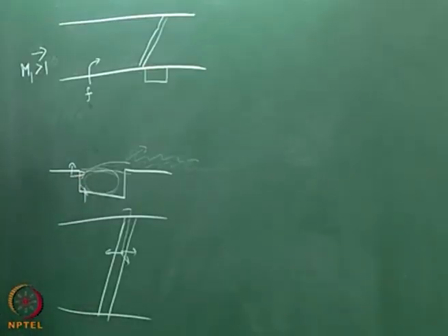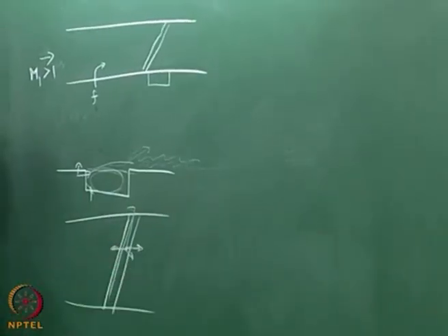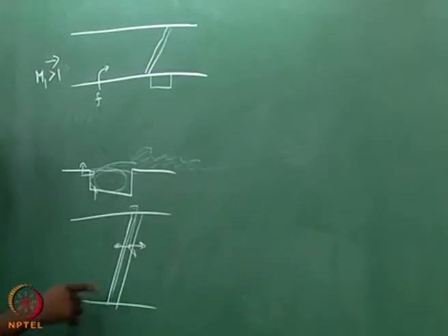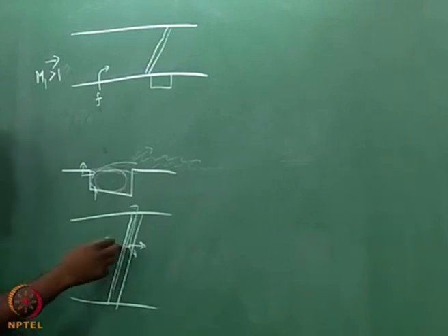Now if I want to use this kind of situation, I have P naught loss more, because I have an object sitting in the supersonic flow, so shocks will be there. We put slant objects so that shocks are lesser, but I have to inject. If I inject along the flow, they are all going together, the velocity difference is less, shear is less, and it is not going to mix very well.